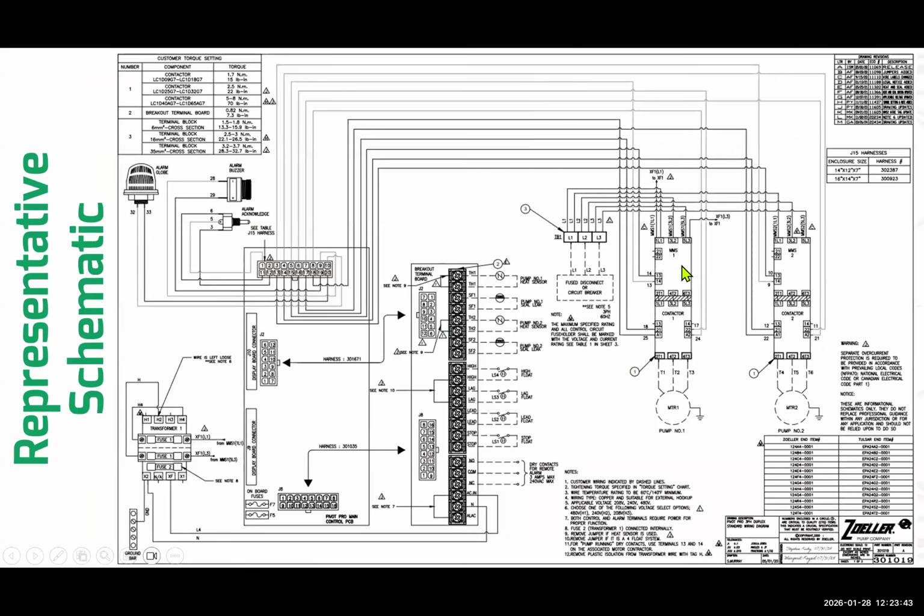If you look at the wiring schematic, this is just a sample wiring schematic that you might see. And there are going to be two of these. One of them is going to be in a packet that's in the box, the carton that contains the panel when you open it. The second, as I mentioned, is in the pocket of the panel itself. So there are two of those in there. Hopefully, one ends up staying with the panel and not getting thrown away as well.